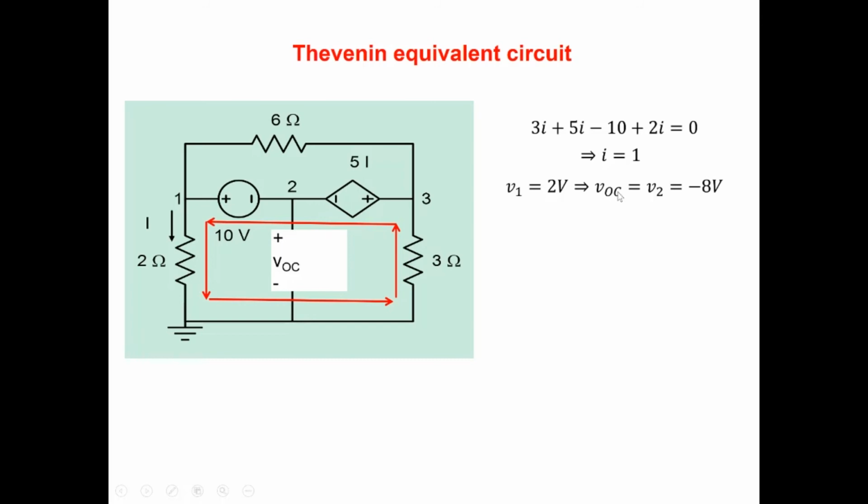The next thing, because there's a dependent current source, we have to find the Thevenin's resistance, and we try to do that by short circuiting the two terminals here. And yeah, I equal to 10 by 2, 5 amperes here. Okay, so let's remove this, let's short it, and our goal now is to find out what is the short circuit current.